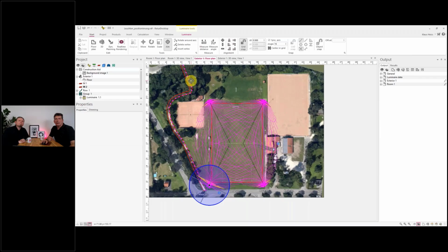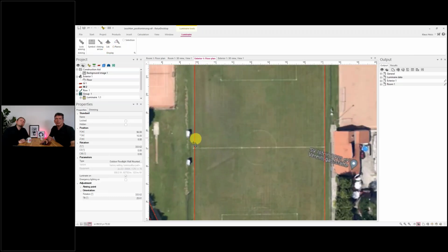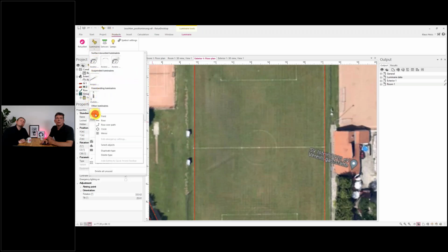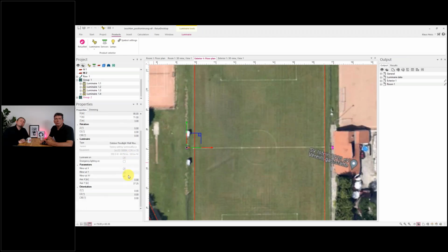Also, this must not only be made for 4 corners; we also have the possibility to make it just on a single axis. Let me show it. I go back to my luminaires, repeat this command, and now place starting from here to this point on the same line. Here we can switch off, because in this example I just want a mirroring.